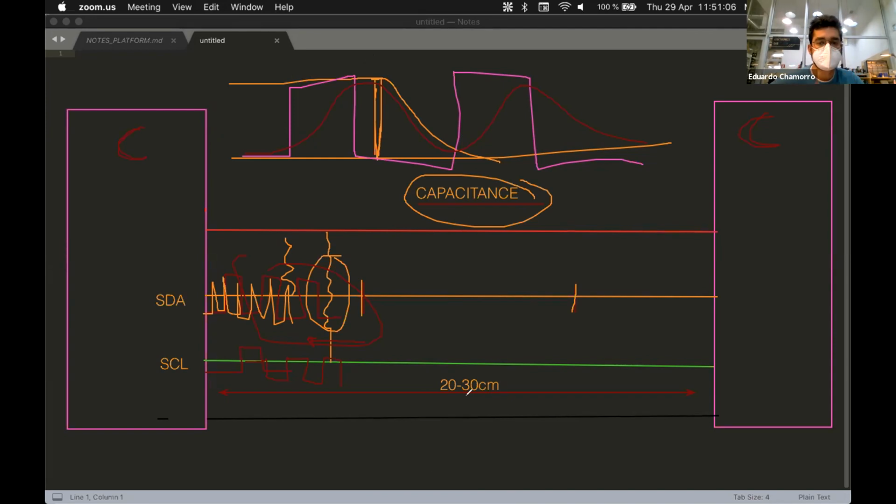If you have long cables, that's not the end of the world. You can also change the value of these resistors, which we normally tell you are 10K ohms by default, but that's not the case. That is a standard value, but they could be as low as 1K or even lower, depending. Normally these values are more around 3 to 5K if we actually calculated how it should be.